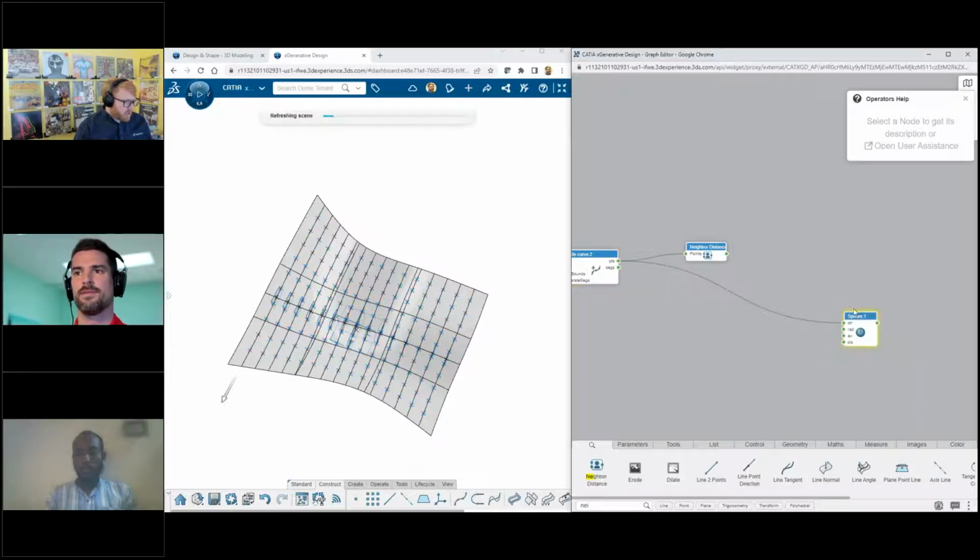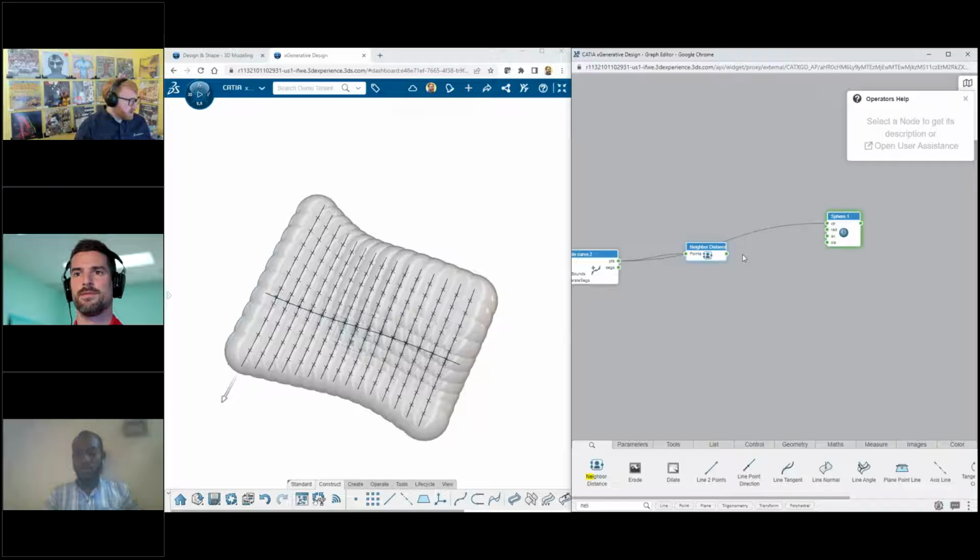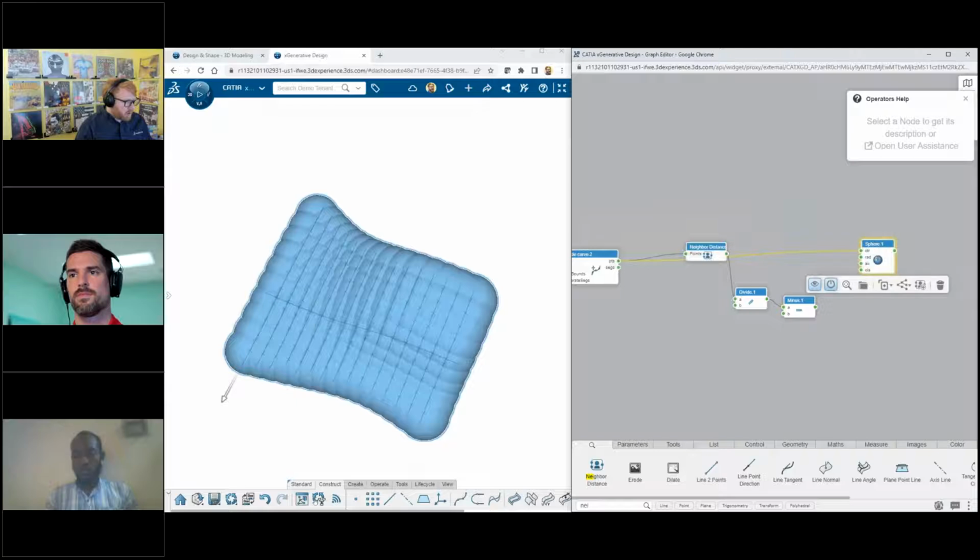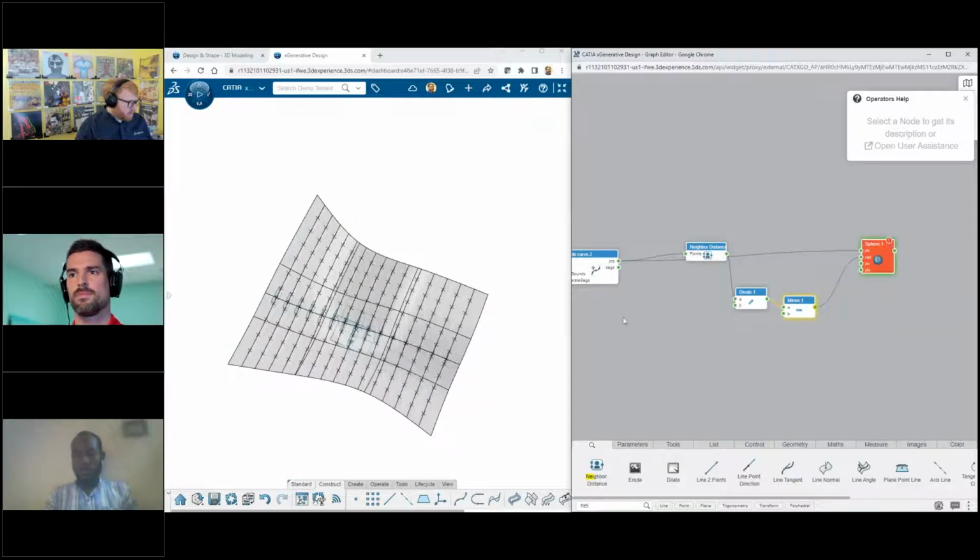Sphere center radius. So there's the center. And then I could say the radius is going to be the distance to the nearest neighbor divided by 2. And then maybe I want some sort of buffer, so I'm going to say minus 1 millimeter. And then I could plug that into radius. And it doesn't work because the structure's incompatible, the behavior's unpredictable.